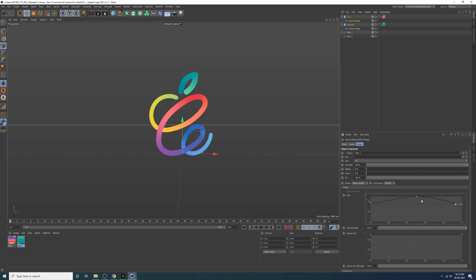I think there is something better than this. I'm just pressing Control Z and deleting this center point. It's better to just choose this handle, select this and change the handle like this. Then you will get more width on the center of our logo. Then change the beginning, something like this. Now you can add a new point by holding the Control key and clicking.